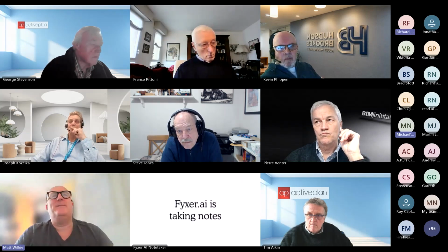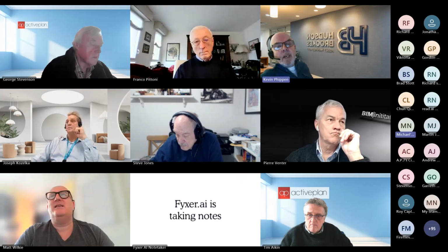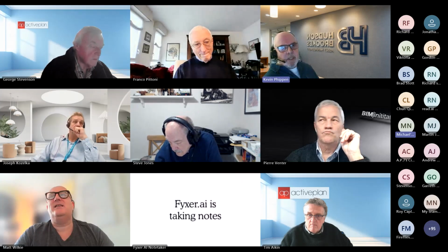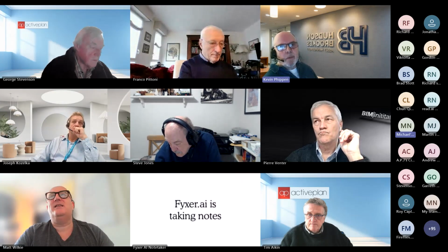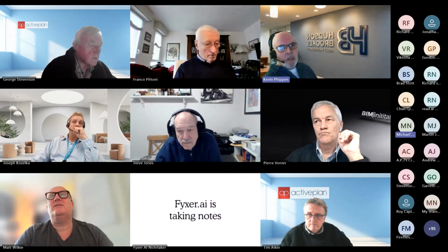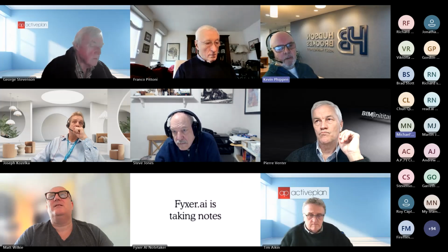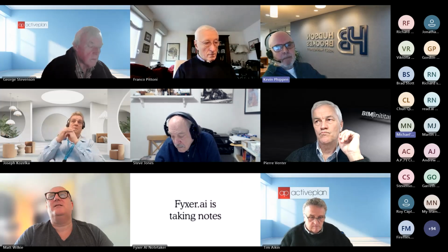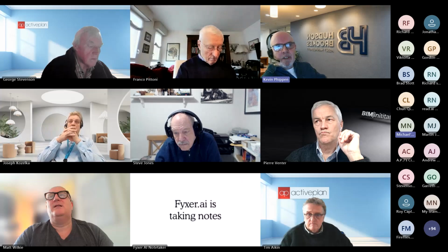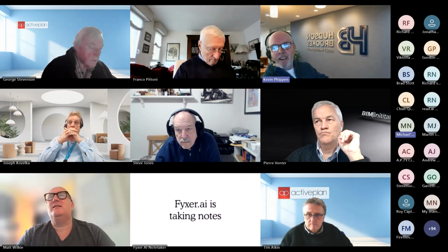Yeah, sure. Kevin. I was going to say, Matt, just commenting on the things you've said, I would totally agree with all those issues in terms of moving walls and being on top of it. But I also say within hospitals especially, the fire strategy is very different, because it often doesn't involve evacuating the building. It could mean keeping people in the building and diverting people around them, because it might be more risky to move them from intensive care to the outside than it would be to leave them in the building.